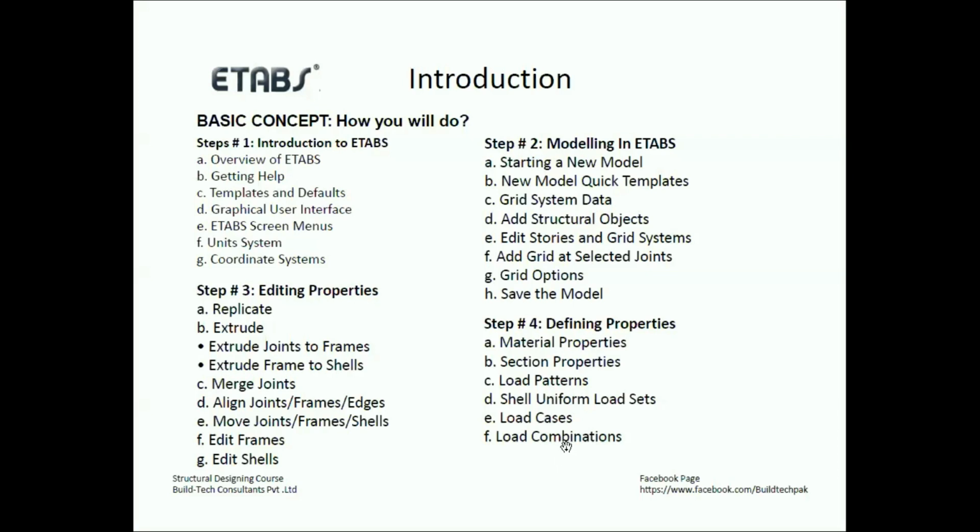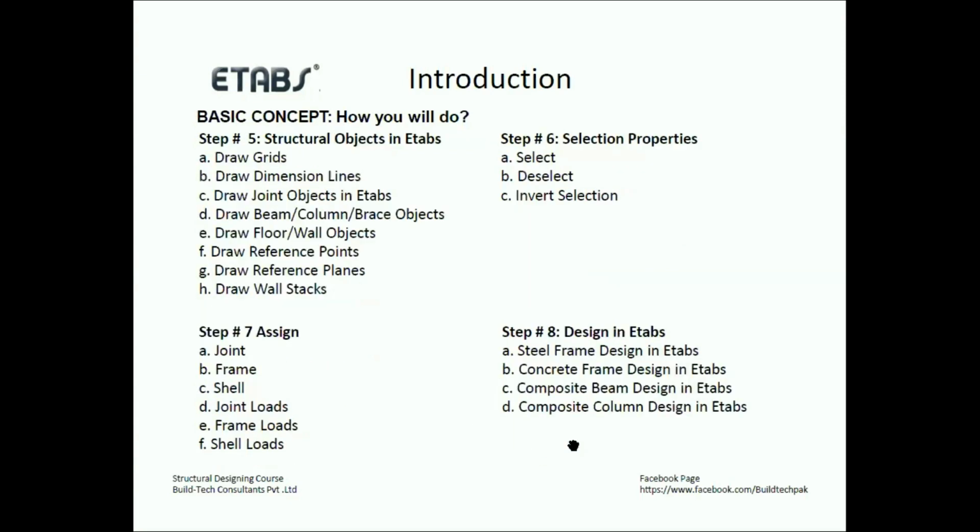The purpose of these load combinations is to simulate different possible worst scenarios that the structure will experience in its service life. Every structure has a design life. For example, buildings have 30 years, bridges 50 years, and railway structures have 100-year lives. During their service life, they experience some worst scenarios. All these scenarios should be simulated in these FEM softwares through these load combinations.